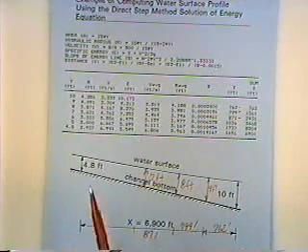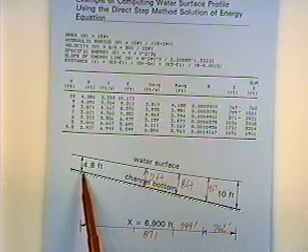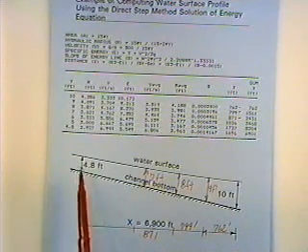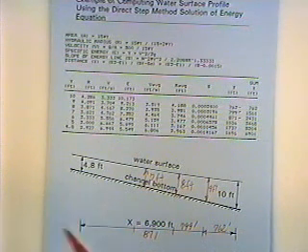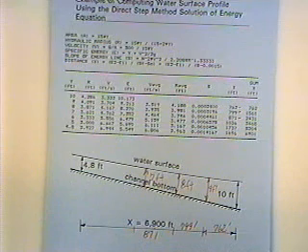And so we've got the water surface profile. We've got the depths at different locations, and then we get uniform flow, and once we get to uniform flow, it stays at 4.8 feet all the way upstream until something changes. The slope breaks, the width changes, some backwater effect, or something of that nature.